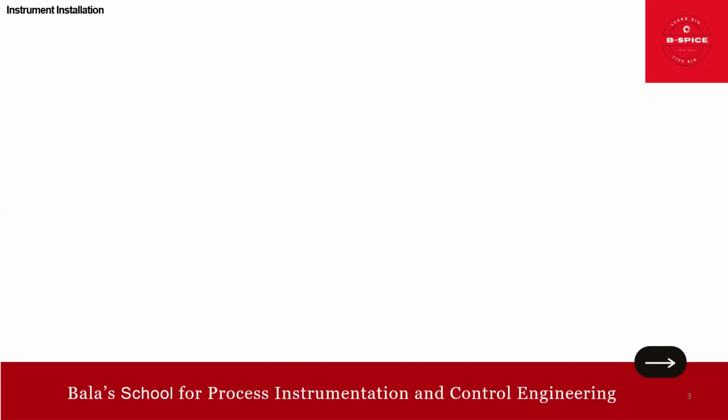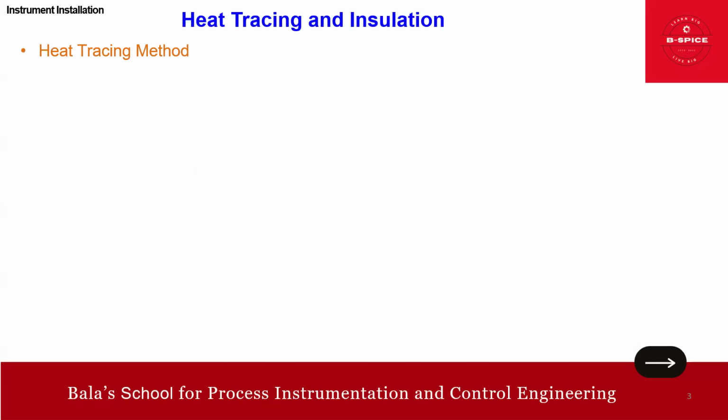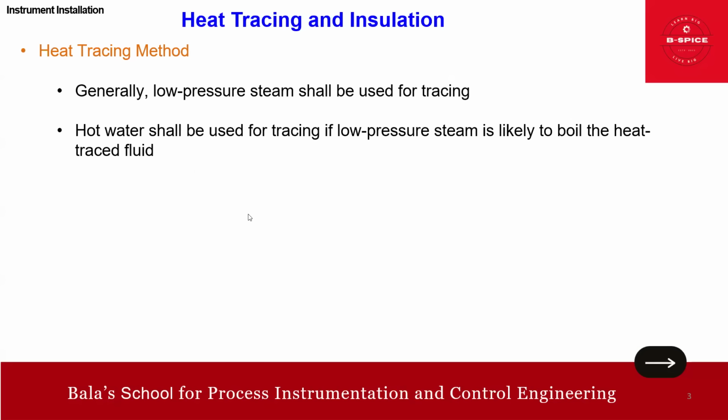Right. Let's go into the agenda details. Heat tracing and installation. What is the heat tracing method? Generally, low pressure steam shall be used for tracing. Hot water shall be used for tracing if low pressure steam is likely to boil the heat traced fluid. That's it. You understand, friends?